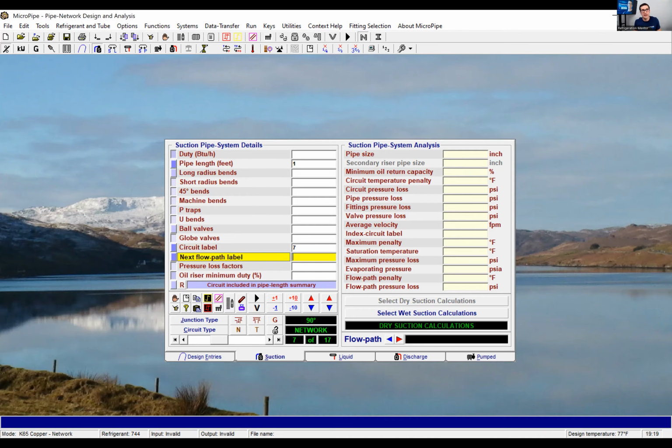And there is definitely an art to designing refrigeration pipework, which I've learned over the last few months working with James. There's different ways to do it. It's like refrigeration, there's not only one way to design it. One designer will design it where they want maybe this amount of pressure drop, this amount of efficiency, this size of pipework. That works, and there's not one size fits all, because I've heard the conversation about yes or no, that's the way it works, that's not the way it works. But one of the things that I do know, you do not want large pressure drops in your suction line, because that oil is not going to come back.